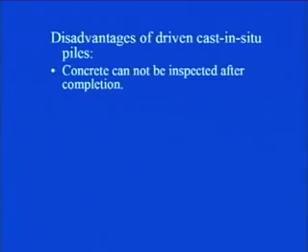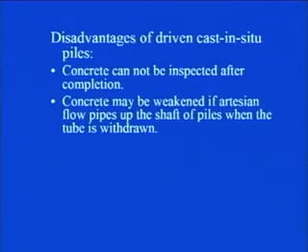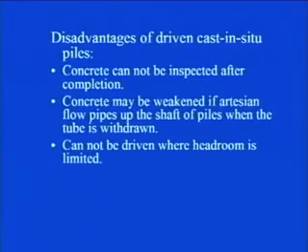Then concrete cannot be inspected after completion. Concrete may be weakened if artesian flow pipes up the shaft of the pile when the tube is withdrawn. When the concrete is weakened, obviously the pile bearing capacity will decrease. So, that is not desirable, and it becomes one of the disadvantages of driven cast in situ piles.